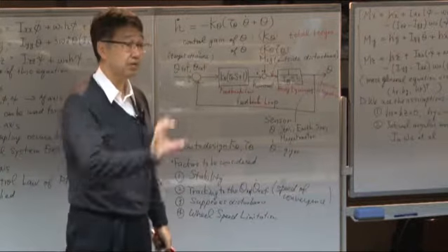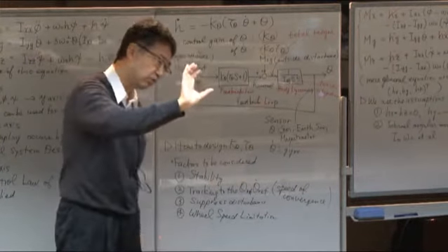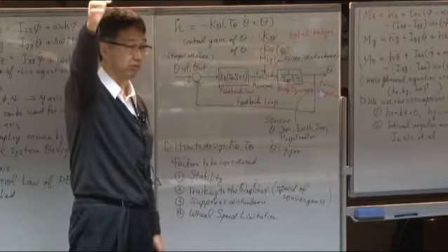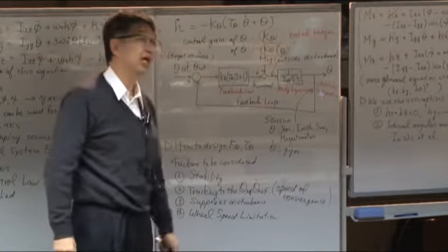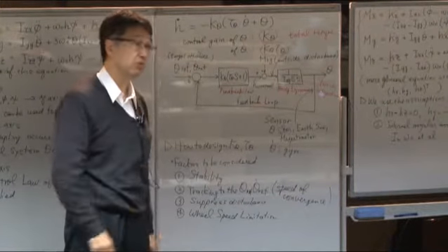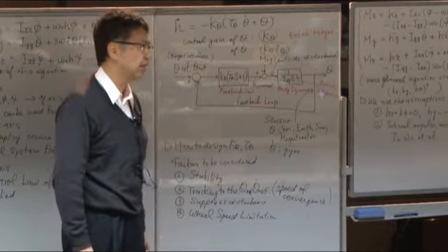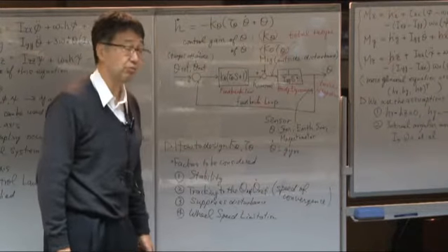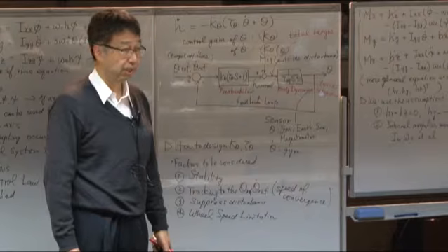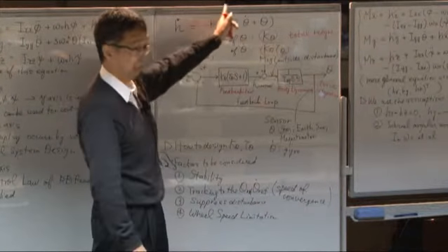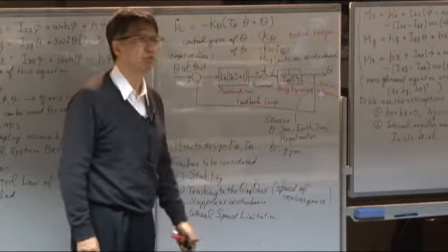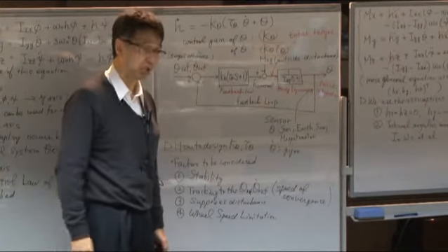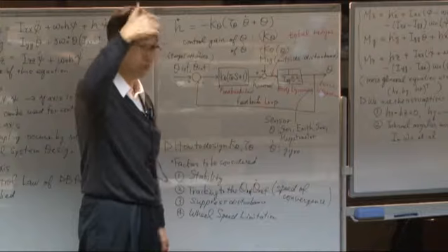then sometimes the rotational speed of the wheel may be very large. Usually the wheel rotational speed limitation is something like 6,000 RPM or 10,000 RPM and so on. But by continually applying this kind of control law, sometimes the reaction wheel speed may reach that limitation.